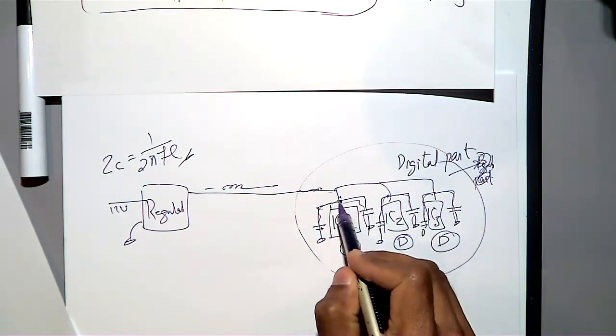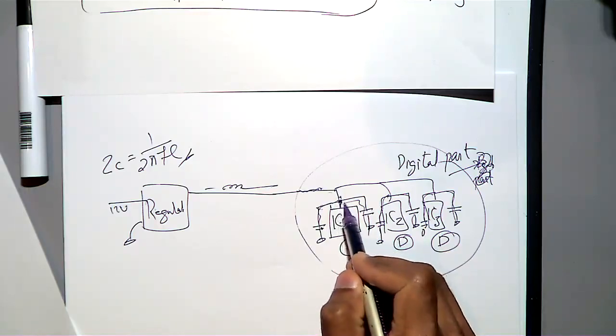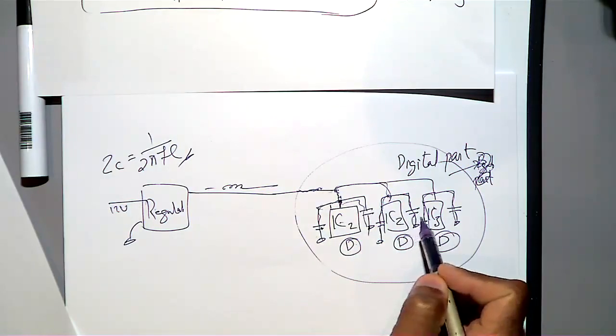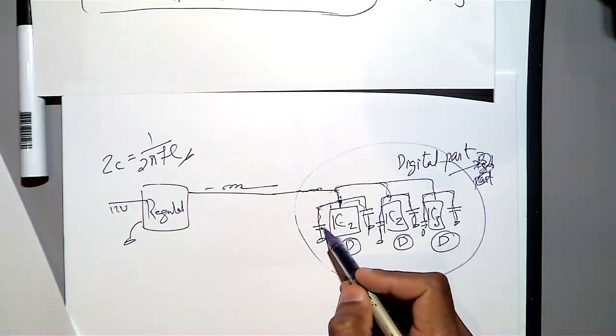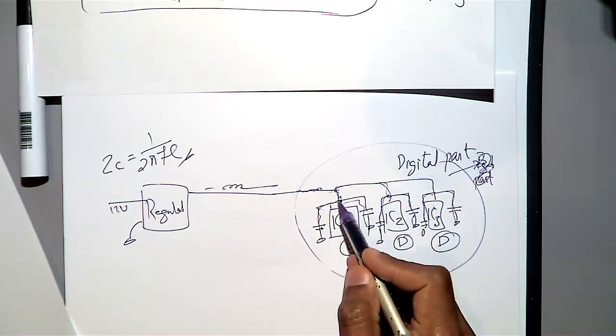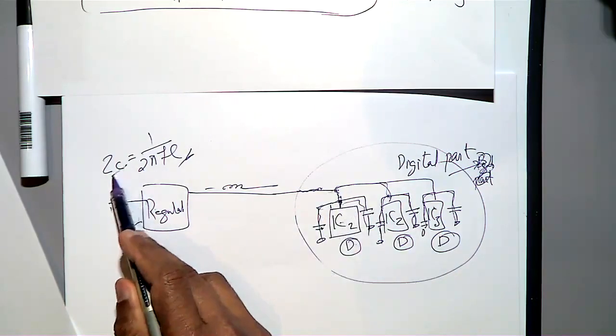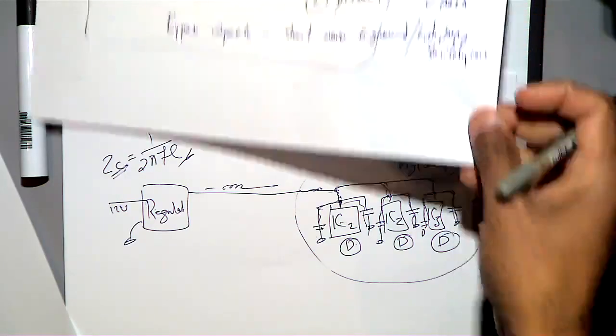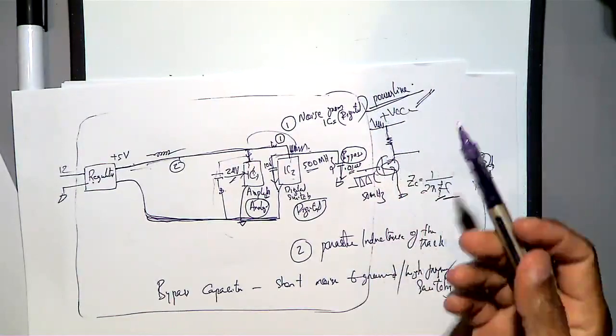For example, this frequency component will come here, and then it will look for the low impedance path for that frequency component. If this is not the low impedance one, it will go elsewhere. You know what I meant? So these capacitors are designed in such a way that particular frequency components go to the low impedance path. So when you have multiple, they put 2 or 3 around the IC, because one will be more favorable to some frequency components. That's the reason the manufacturer recommends it. So this solved one issue, the noise from the power line.